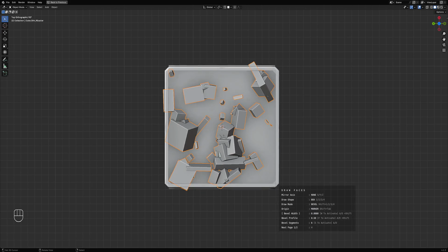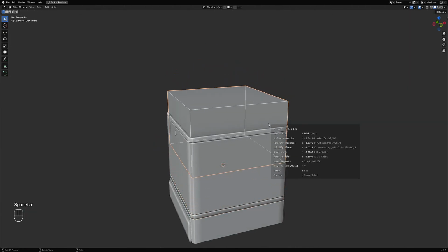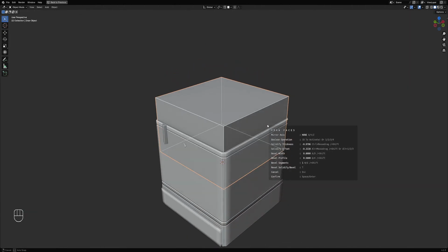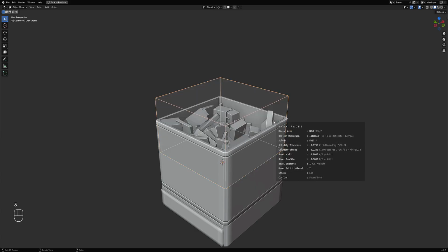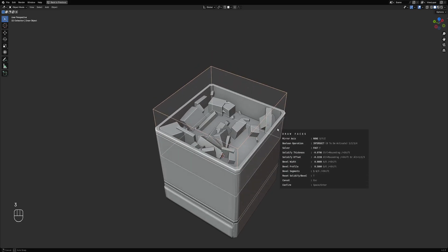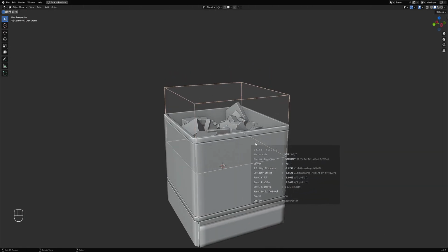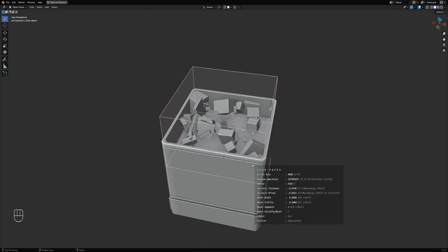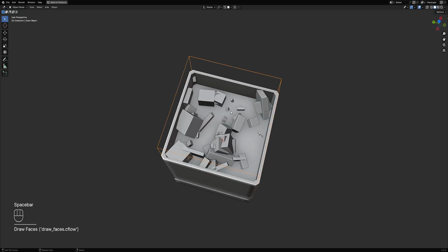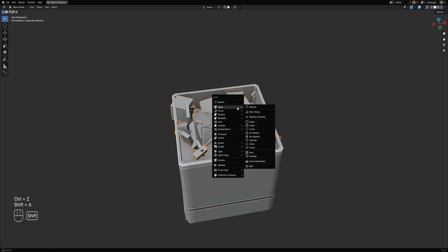Make sure there's a little bit of overlap for space to confirm the shape. And while in the second mode, use number 3 for the intersect boolean. You can see that the overlap or the clipping geometry in this part here are green. Okay, that's for drawing.